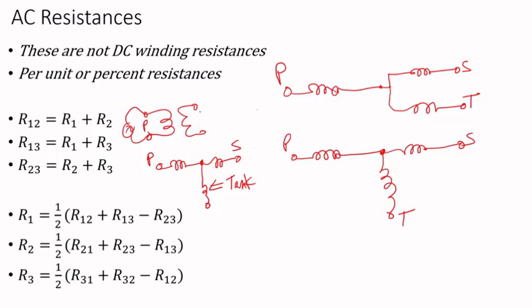But anyway, assuming this is connected to a load, for instance, you have the core, and I'm assuming core form here. So the windings are wound around the core leg or legs. This winding will establish flux in the core, and that flux will induce voltage in the other winding.